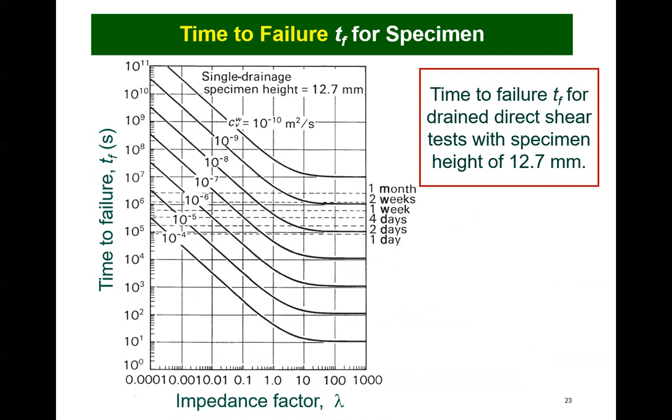One of the difficult aspects related to testing unsaturated soils is the length of time required to run the test. As soon as the soil becomes unsaturated, its coefficient of permeability can decrease by orders of magnitude. This in turn means that the time required to perform a direct shear test will increase by orders of magnitude. The ceramic high air entry disc also has a low permeability, which further impedes the equalization of the pore-water pressures.